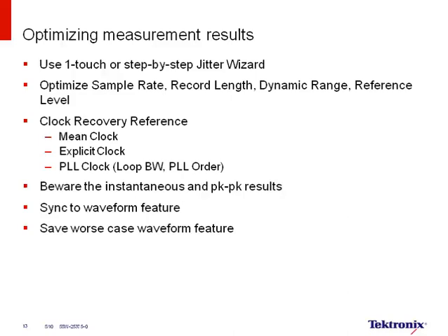So when you write or create a document or a jitter characterization report, you might want to capture how this measurement is done. For example, you might want to say, this peak-to-peak measurement of, let's say, 99 picoseconds was made with a population size of 10,000 after a period of so much.